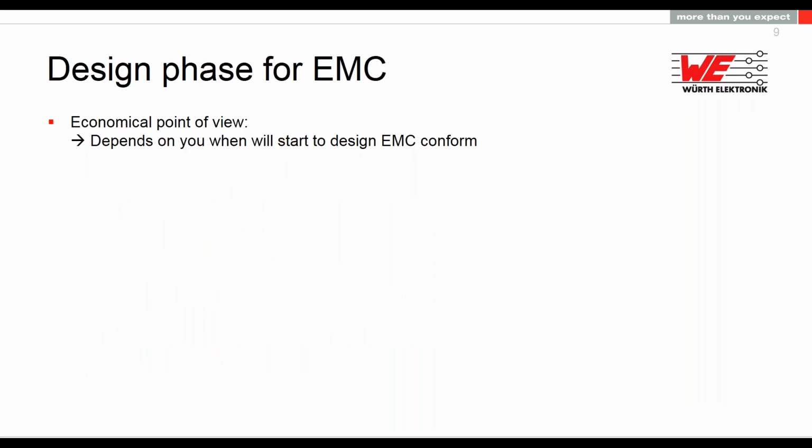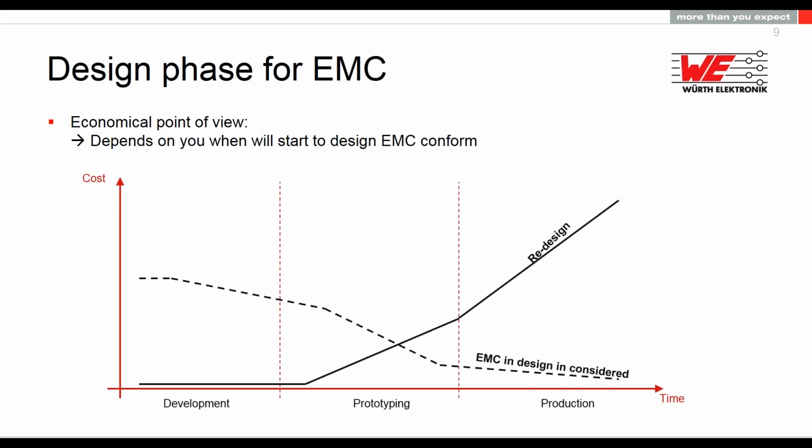Well, it's very important when you start to design the EMC in your device, because when you just focus on your function and you finish your design and you make the housing and everything, and then before you start to sell it, you go to the EMC lab and you find out, oh my God, I have to improve something because I am above the limit. Well, that's actually too late, and it's very expensive, especially when you have to redesign the whole board.